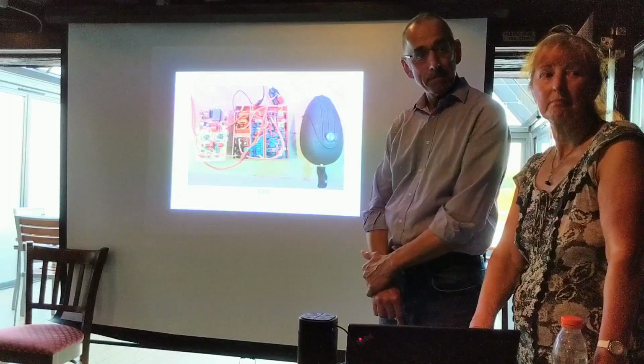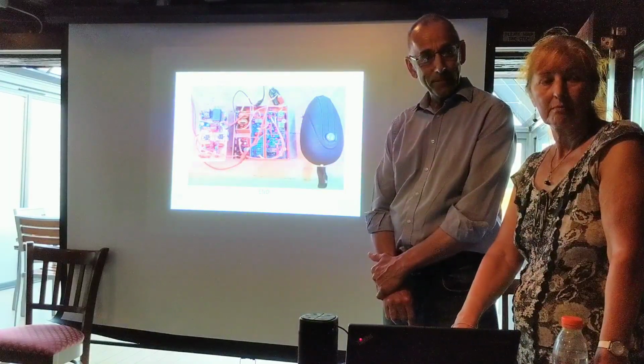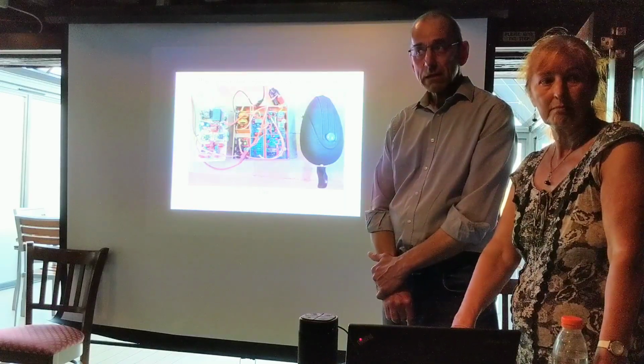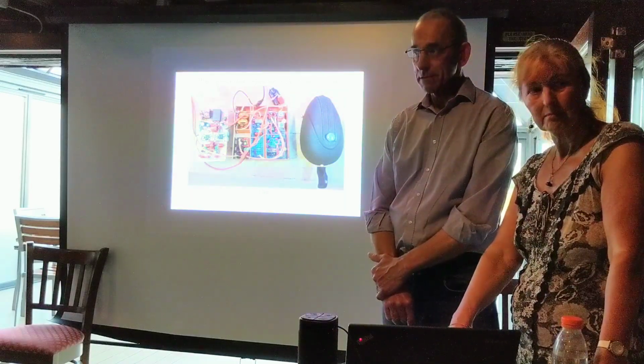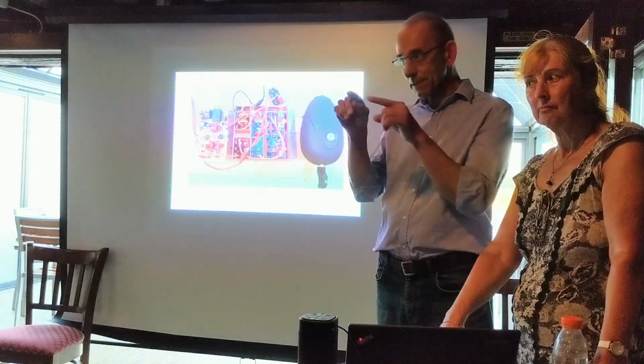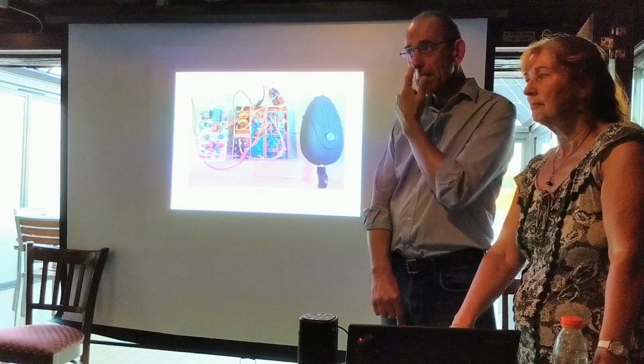I'm not getting good results with a low pass filter. So the bandpass filter seems to be a much better idea, because there's submarine transmissions very close to that, and I really had to peak that up so that the submarine transmissions were on the skirts of that wave shape.